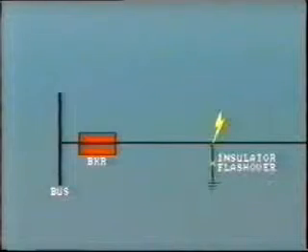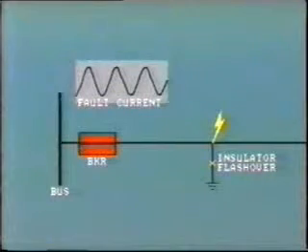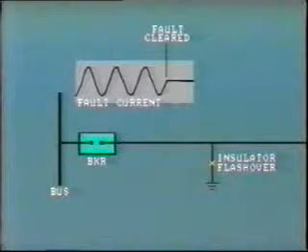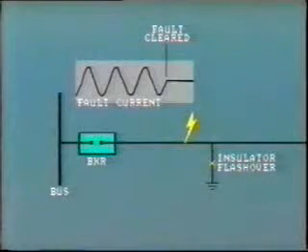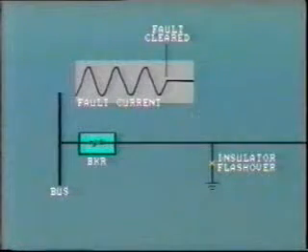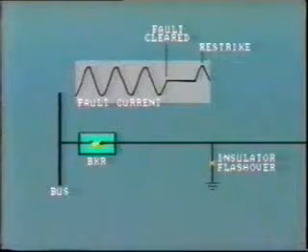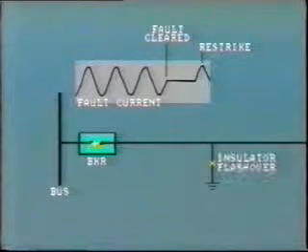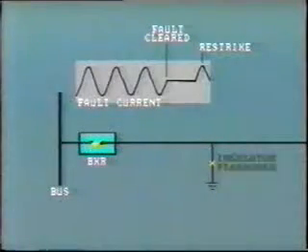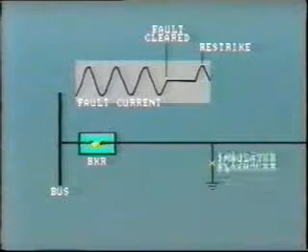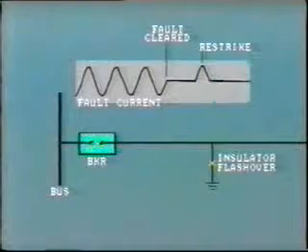Well, here's one way. A lightning strike to a phase conductor flashes over an insulator, causing a single line-to-ground fault. The breaker at the substation successfully clears the fault, but a very short time later, perhaps a few cycles, there is a second strike to the line. The resulting surge in voltage causes the open breaker contacts to restrike. But in only a few cycles, the ionized gases from the original fault have not had enough time to dissipate. So the original fault reestablishes itself. Usually, the fault current will go out at the next current zero after a half cycle.